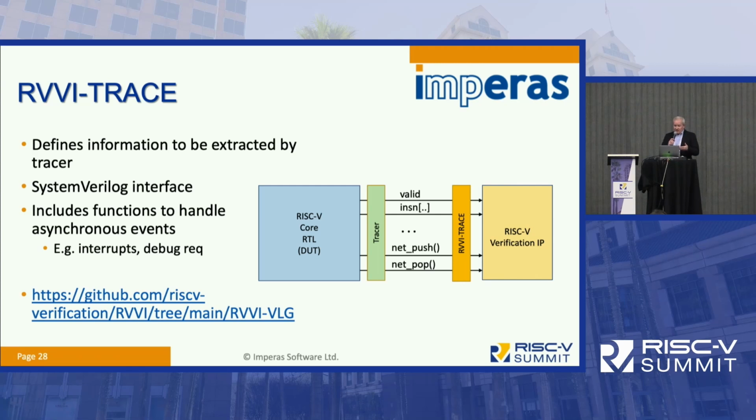It's built as a SystemVerilog interface. It supports the data in terms of the state, so your general purpose registers, CSRs, FPRs, vector registers, and it also handles your asynchronous signals as well in order to communicate those across. Also, the dimensions of this interface are such that if you have a device under test which is multi-hart, multi-issue, the interface can be dimensioned in order to support that as well.